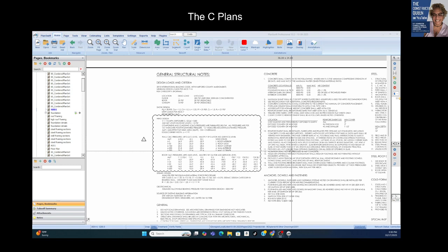And we keep going down, right? And that weight is distributed into what? The concrete foundation. And then, of course, that whole load is distributed into the earth. So the vertical path again is the roof to the beams, to the columns and structural walls, down to the concrete foundation and into the earth. And so that's the vertical path.